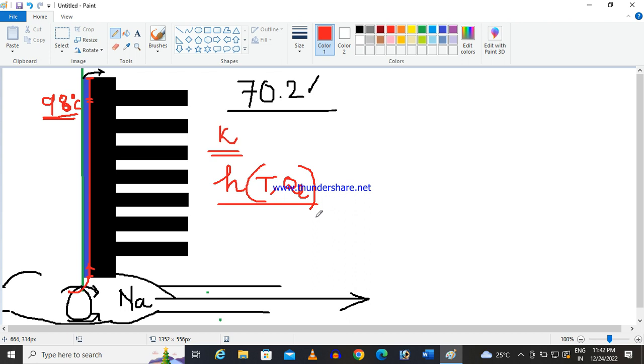And another thing I was telling: if the geometry is standard, like spherical or rectangular, where the characteristic length is known, there we can apply the conventional regression formula of the Nusselt number to estimate the convective heat transfer coefficient. But here you see the geometry is very complicated, where one fin is stacked over another. Then how to estimate that heat transfer coefficient? The challenge is there. So I'm not going to give you the exact dimensions. I have developed one fin and it is validated.